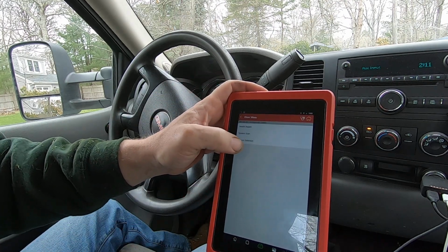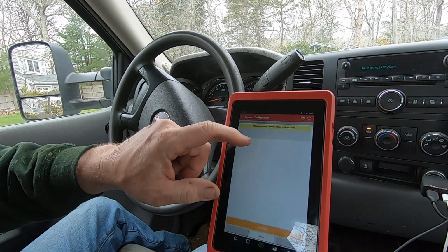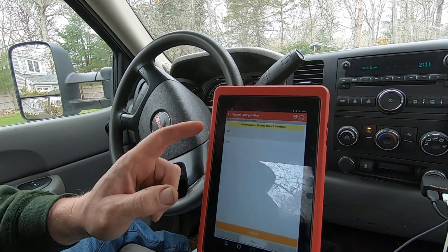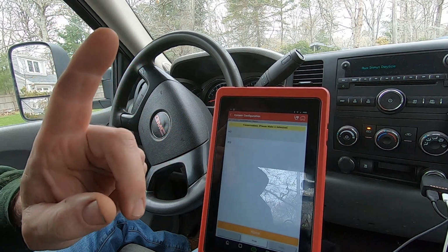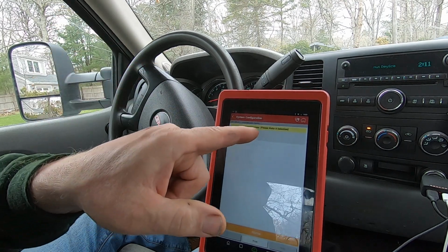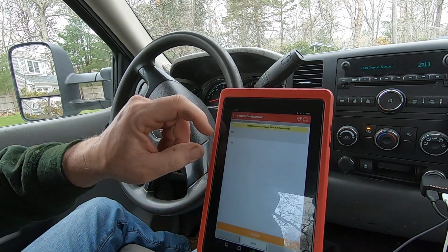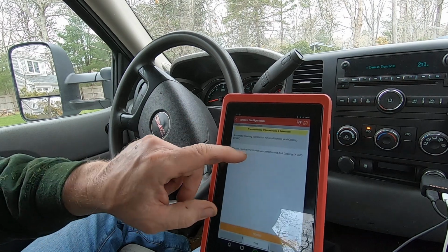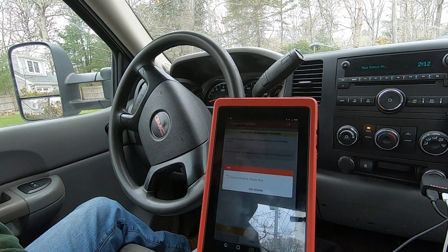I want to do system selection. It's a 6-speed automatic. This just says transmissions, please make a selection, but having my prior scan tool, it usually asks this if it's an auto transfer case, and I think somehow they made an error in the software. So I have a manual lever for the transfer case, so I'm just going to hit no. Manual heating and venting, doesn't have the screen on it.